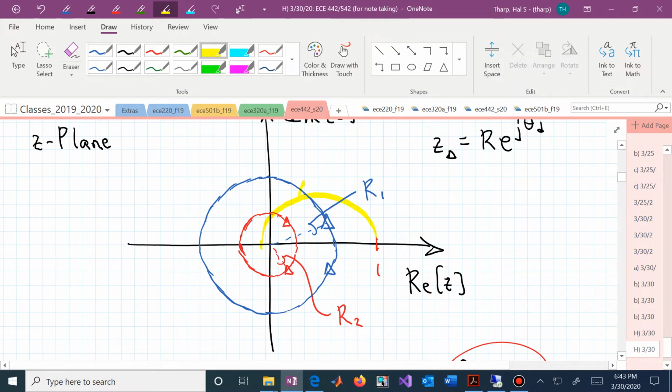So if they simultaneously satisfied those specifications, then you would have just the intersection point resulting from the percent overshoot logarithmic spiral or heart shape, and these circles. If you had a peak time spec, then you're looking at particular angles where the larger angle corresponds to a faster response or quicker to the peak behavior.